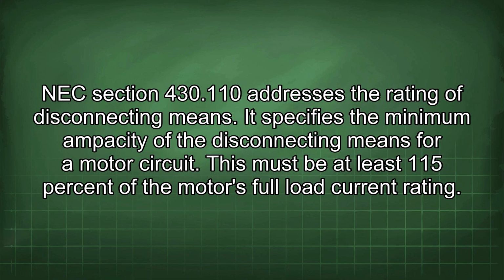NEC Section 430.110 addresses the rating of disconnecting means. It specifies the minimum ampacity of the disconnecting means for a motor circuit. This must be at least 115% of the motor's full load current rating.